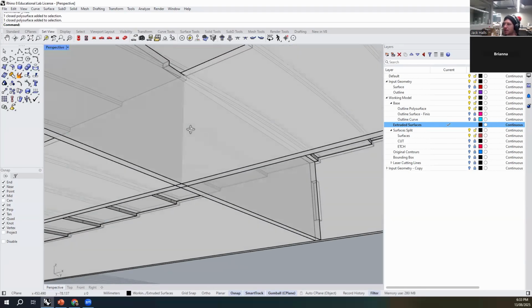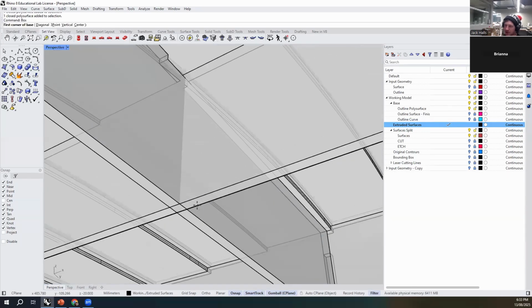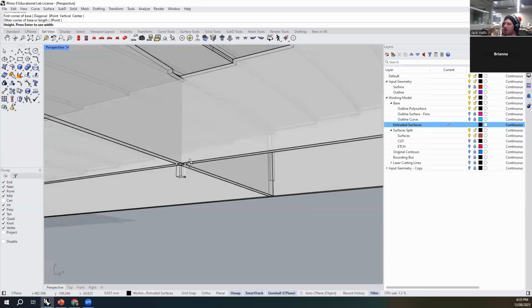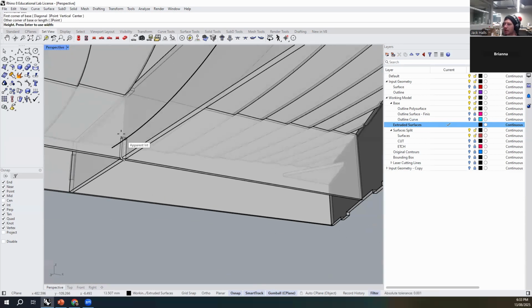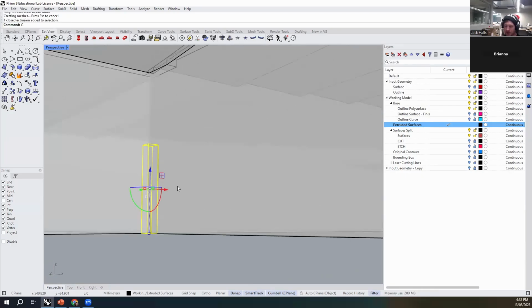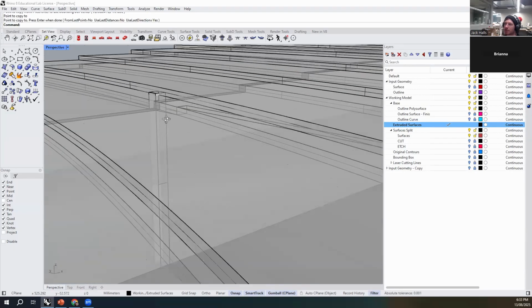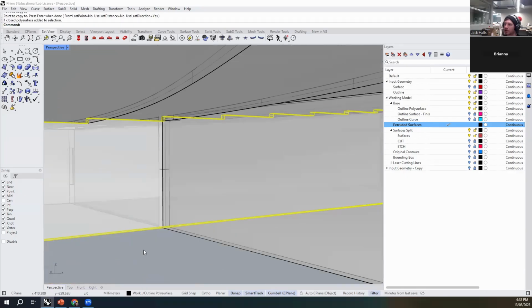So obviously these pieces don't just fly through each other, and the logic is very much the same. It's going to be our box command, arbitrary, I suppose. It doesn't matter too much. As long as what we do next is to copy this, and we're going to hit M vertical, grab a corner, drag it up, making sure that it's going through these components all the way.